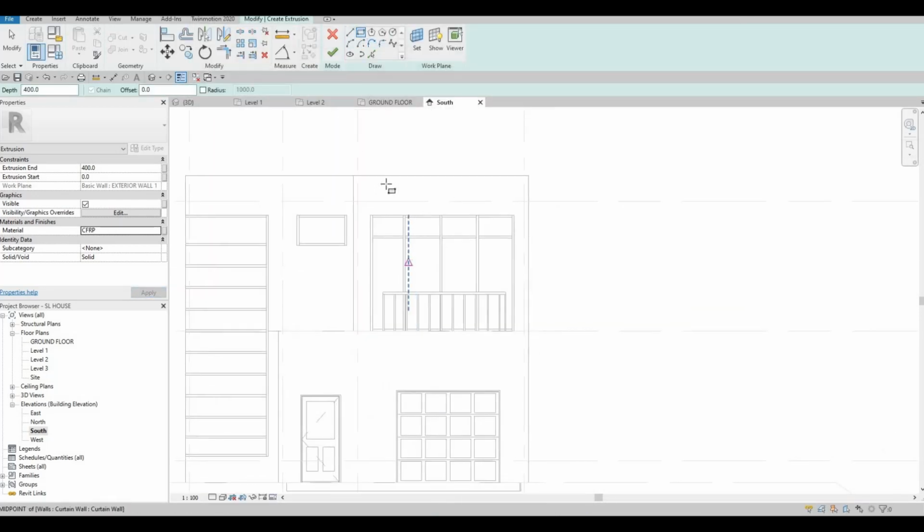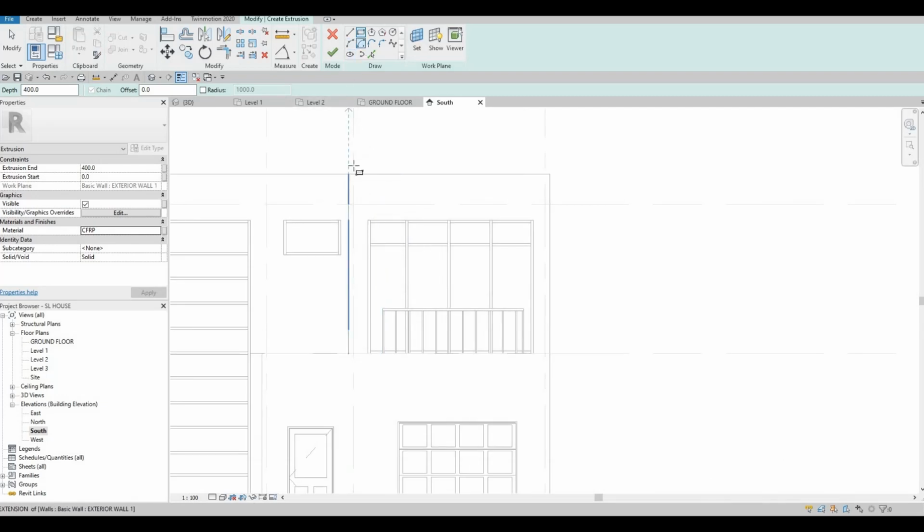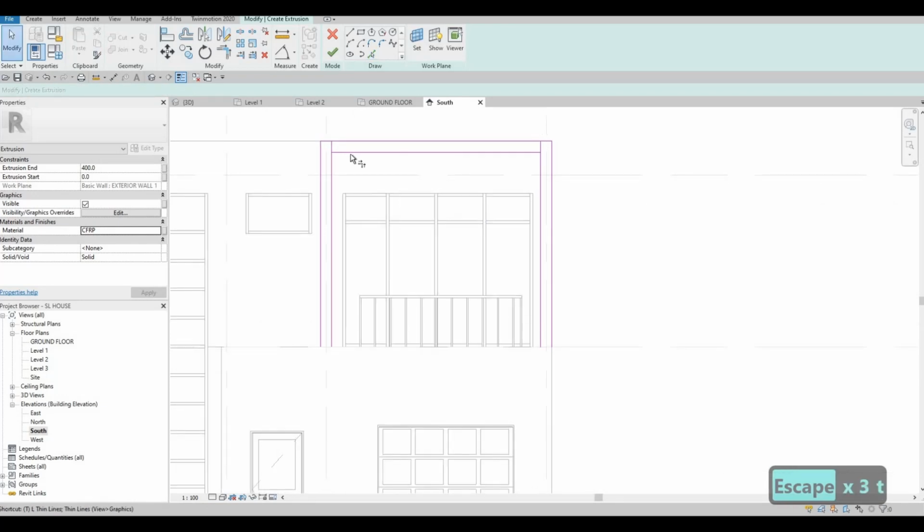And then here we're going to add our design. So what I usually do is we can pick this line if we want to, and then trim and extend, and then here pick it again, offset this one to 200. We could do that. You can also use rectangle if you want to, but it's up to you to decide what you're gonna use. Things that make your life easy is the best.